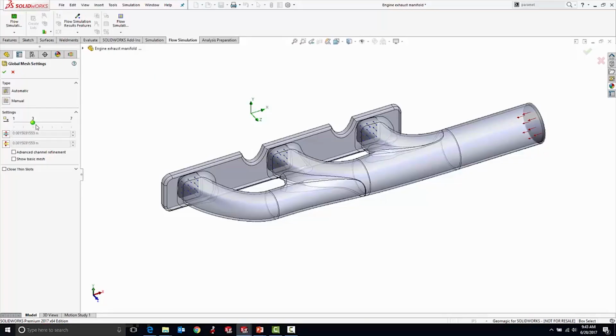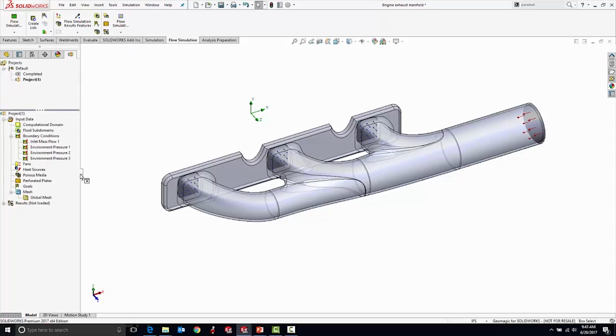We're tracking the fluid that comes in and out of those little volumes. If I push my slider bar to the right, I'm going to get a larger number of smaller chunks, right? That's going to give me more accurate results, but it's also going to take longer to calculate because there's more of them for the computer to do. So I'm going to leave that alone for right now, just where it is.